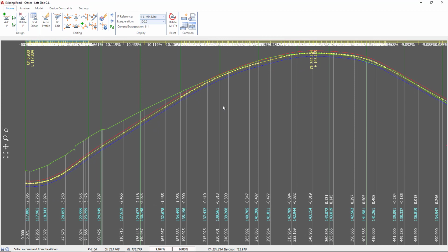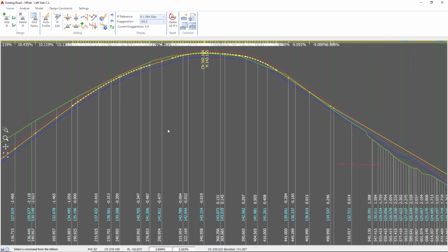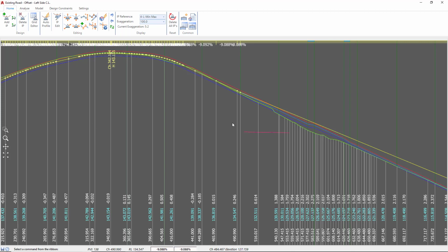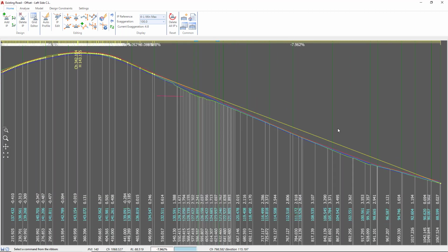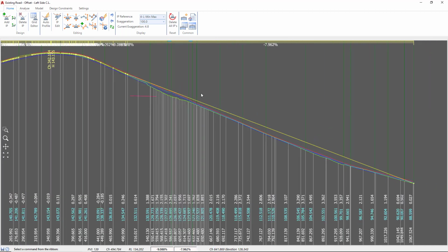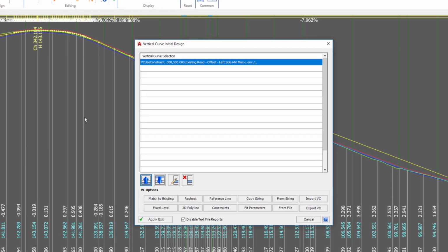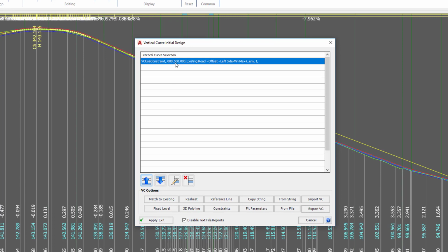What you'll now see in the vertical grading editor is the software has matched all of the available cross-section points onto our design for the first 500 feet. Now we could say for the remainder of the design to match onto the constraint at -5%. So at this point we can go back to Auto Profile. Rather than edit the entry we've already got, we want to keep that.